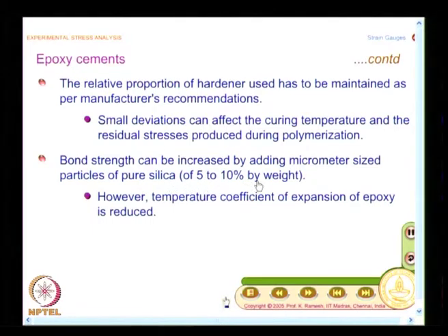You have in photoelastic coating also that kind of adhesive, which permits smooth transfer of strain from the base material to the strain gauge. You need to have a high bond strength. For high strain applications, it is better that strain transfer is done without loss.